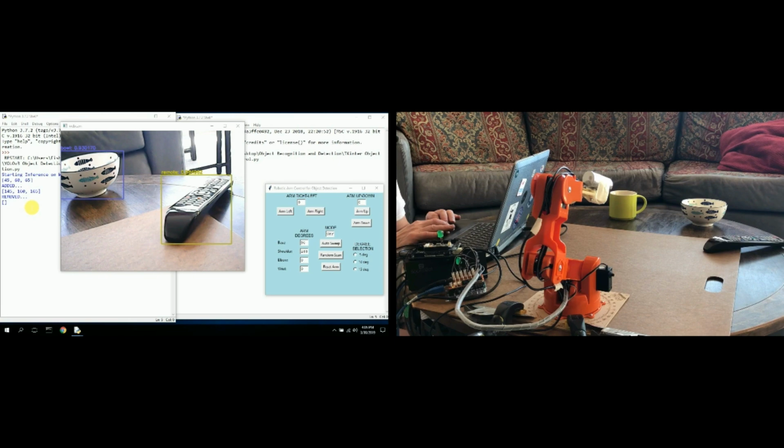For instance, in this Python shell over here for object detection and recognition, these are items that it has added to the screen, seen on the screen, and added, and then said out loud using the VR3. And then some items were removed. So as items are removed, I add a 100 to the number and pass that to the Arduino, and the Arduino knows that if it's under 100, the item's being added, so it says added. Otherwise, if it's over 100, it knows it's being removed. So that's pretty simple there.